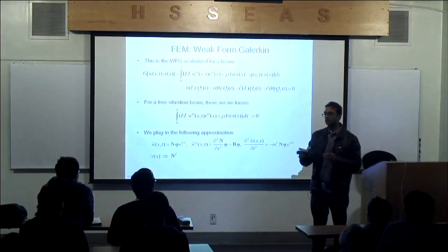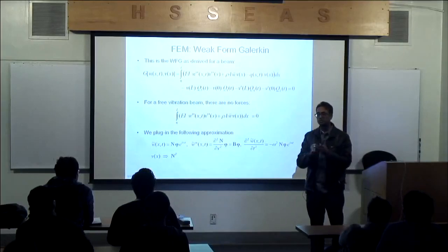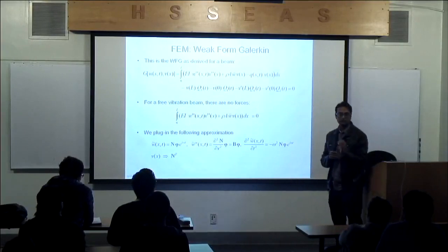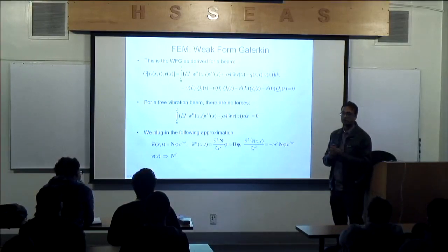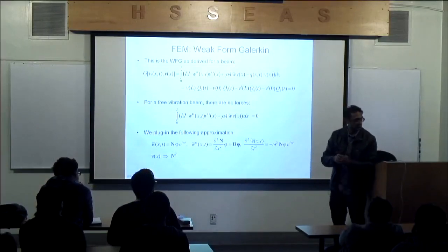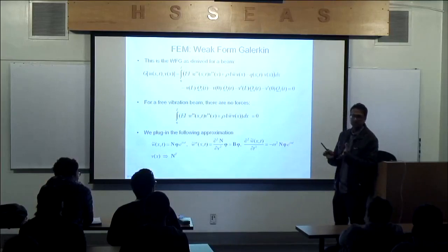We can only impose essential boundary conditions. That's really all we want to do. Okay? We want to constrain the body. We don't have to actually. If you don't constrain the body, then you will have some rigid body modes. And maybe we can actually do an example later on with Abaqus. I don't know if we will get to that, but it will be interesting to remove all the boundary conditions and run it to see what we get. But you should get rigid body motions.